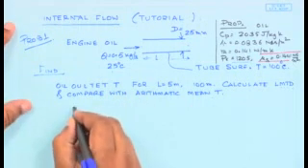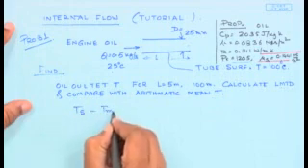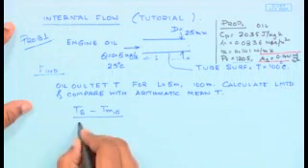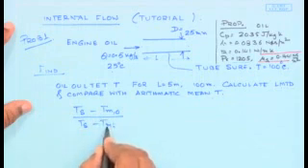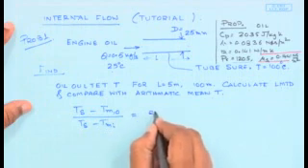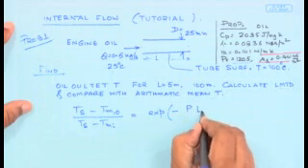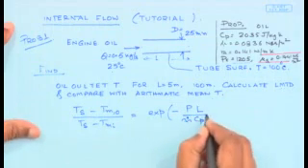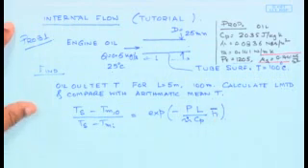So the fundamental equation with which we are going to start is Ts, the temperature of the solid surface of the tube, minus Tm, the mean temperature, divided by Ts minus Tmi, the temperature at the inlet of the fluid flowing through this, is the exponential variation, minus P being the parameter, L being the length, m dot being the flow rate, Cp times the average value of the heat transfer coefficient.